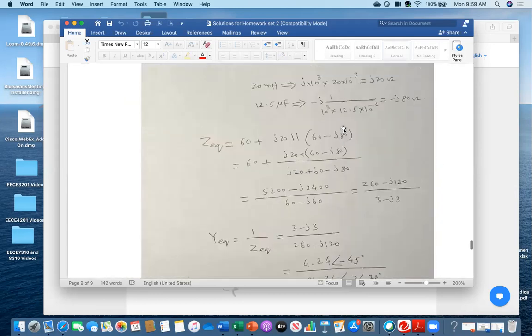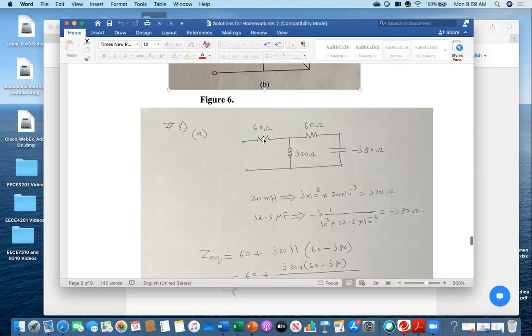The same thing goes for here. If you add this one and this one, that is wrong. When you are giving your eye here, you are looking at this one. So this means this is in series with the rest of the component. That's why you have to start from here. This one in series and then parallel with this one, and that combination is in series with this.